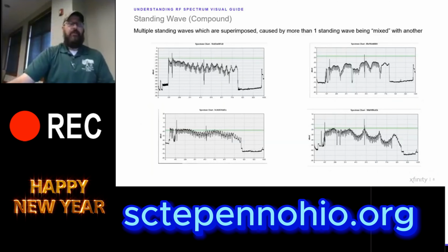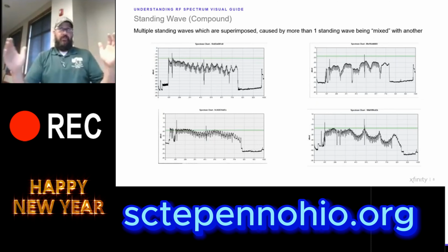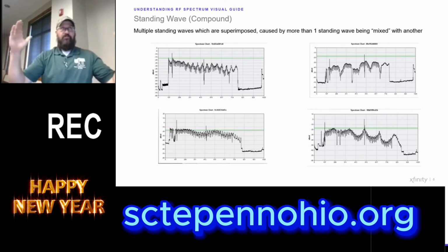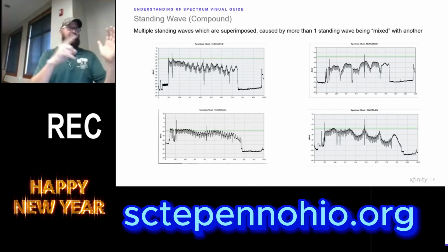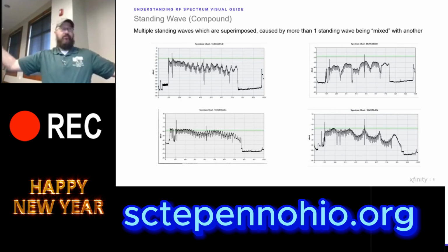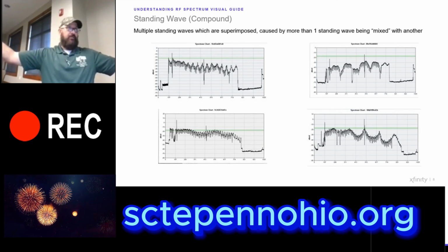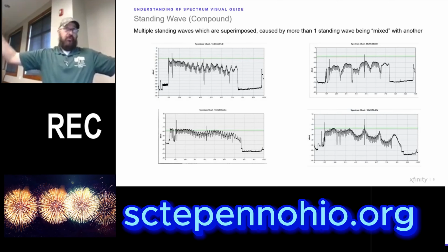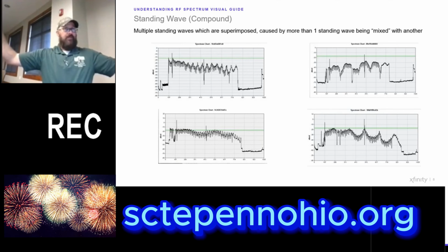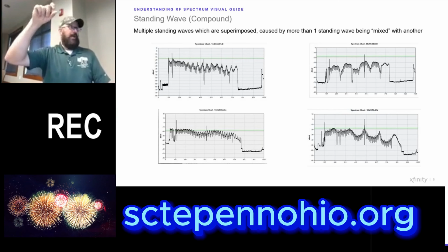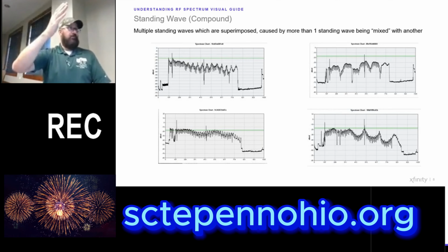So now we can talk about compound standing waves. And as we mentioned, most of our examples just include one reflective cavity, meaning you have one reflector on either end and that cavity size is fixed. Now imagine that you have a span of trunk cable, trunk spacing that's maybe 1,800 feet, okay? Now amplifiers and the connectors on the ends can be pretty natural reflectors. Now let's say out of that 1,800 feet, 600 feet away, you have a radial crack, okay? Now that also becomes a reflector.